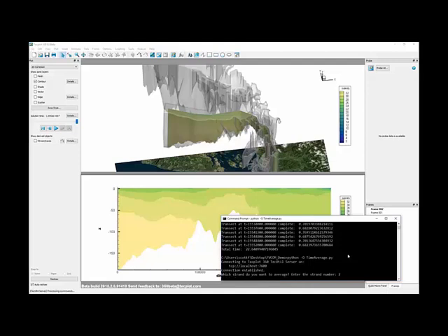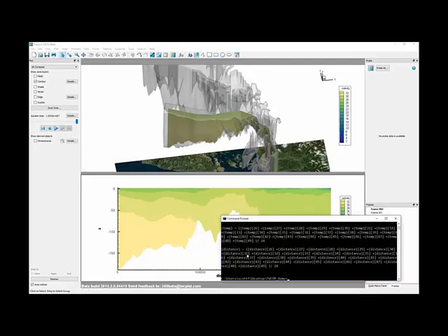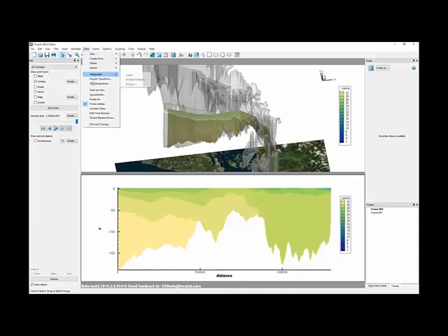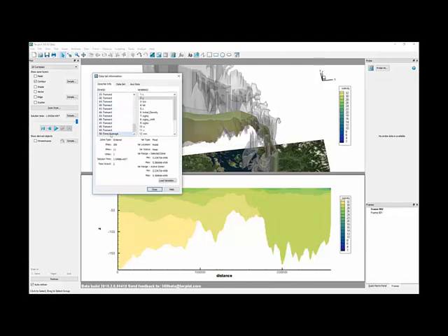Now what this is going to do is it's going to create one new zone and compute the average of all of the other zones. So you can see, for instance, temperature and distance used the Tecplot equation syntax, which we'll go into in a minute, and did the summation of all of my transect zones divided by 24, and we now have a new zone called time average, which has the same grid topology as our transect zone. So you see I of 200, a Jmax of 11. This is the same grid topology, and now all of the variable values here represent the average of the transects.